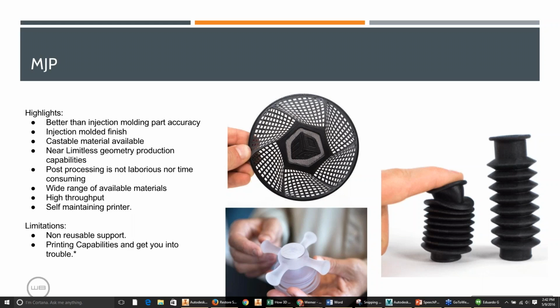So across the board, this is going to give you the best resolution in the entry-level professional spectrum of printers, but be wary. You want to make sure that you always pay attention to the supports that you're going to be using here and factor that into your costing and your budgeting when you do that. Where with color jet printing, support gets completely recycled. In this scenario, it does not. So it's not the best to get economical large parts out of.